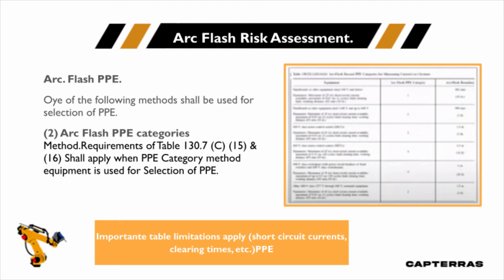So if we look at a typical example, we may sustain an arc down to 38% of the bolted fault current. So I would look at the clearing time and say, okay, if I have a 10,000 amp bolted fault current, I may only have 3,800 amps of arcing current. Is that going to still be within the instantaneous trip range of my breaker to get my 2-cycle clearing time on my, let's say, molded case breaker? So it's important we do pay attention to that.